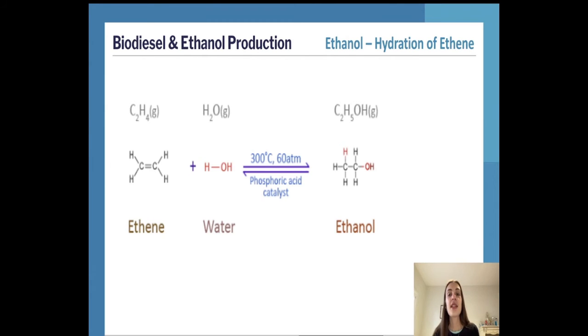We also need to consider that at very high pressures, ethene polymerizes, which means that it makes a very, very long chain molecule, which is called polyethene, which you may have heard of. And so apart from wasting the ethene, which could be made into ethanol, it's also clogging up the plant with these big solid masses, which are not producing what we want to be produced, and hence is just making a mess and actually could cause damage to the plant.